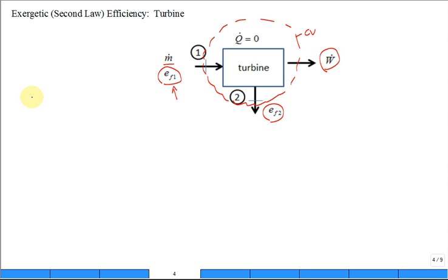All right. So let's do an exergy balance for our system. We can write it down where it's steady state. There's 1 minus T naught over T_B times Q dot, but there's no heat transfer for the turbine. Our most common assumption when you analyze a turbine is it's insulated.